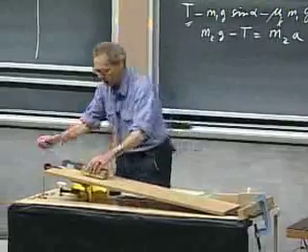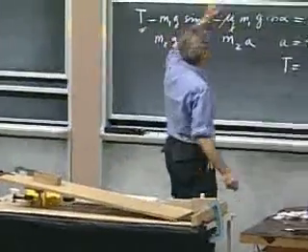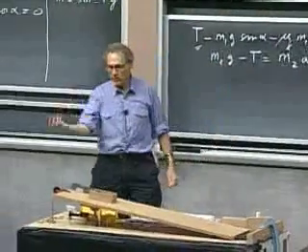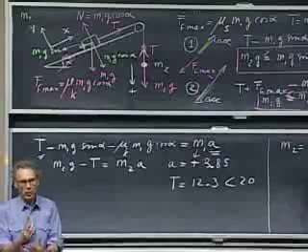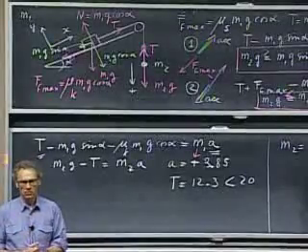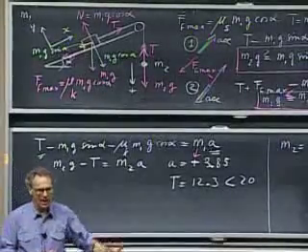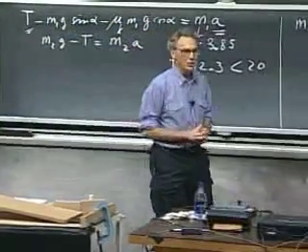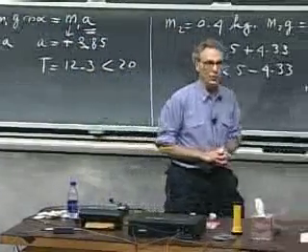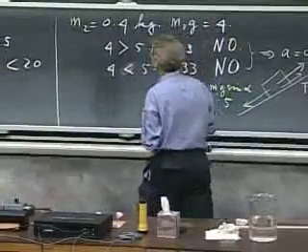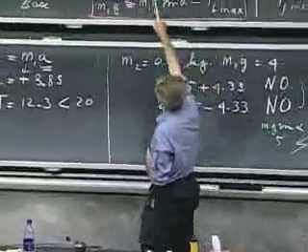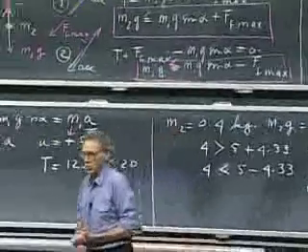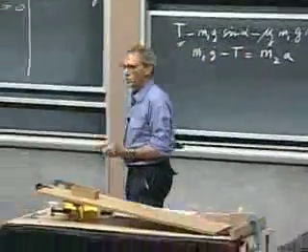Now I'm going to do exactly this experiment. Put a rope over it with a pulley, and put M2 on this side. And now I'm going to load down M2 to the point that it starts to slide uphill. That should allow you to also calculate the friction coefficient. You have all the tools for it, because once you know that it is just at the point of breaking and going uphill, you know that that equal sign of that equation holds. And so you should be able to calculate the friction coefficient.